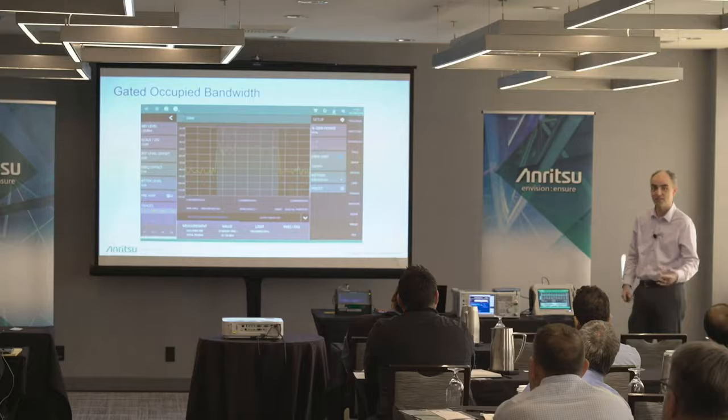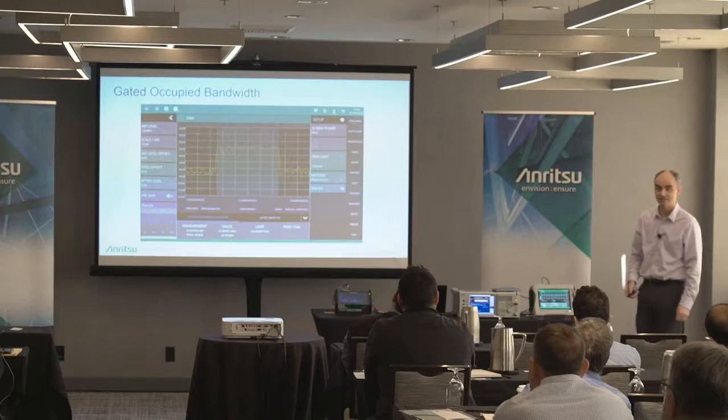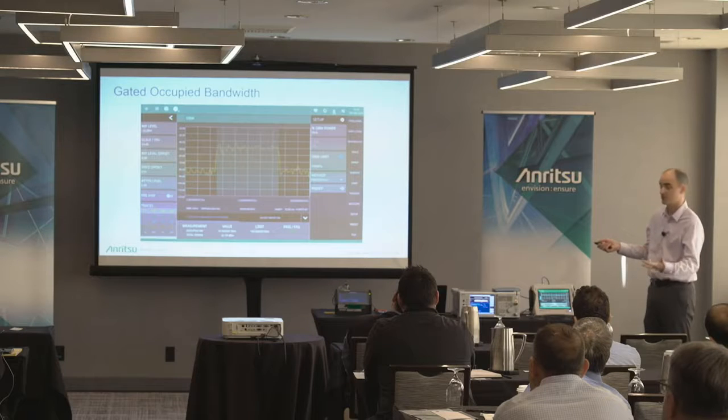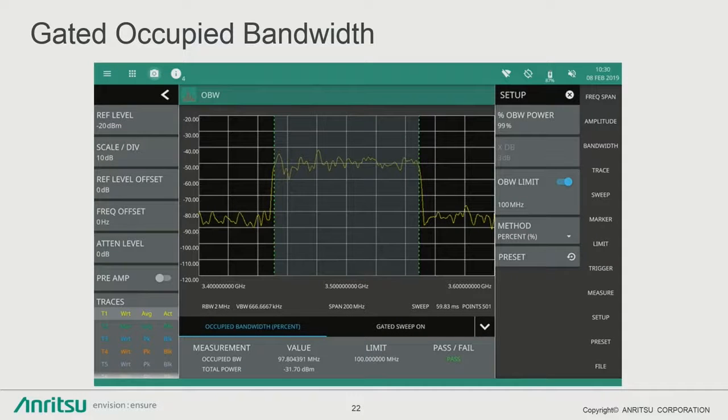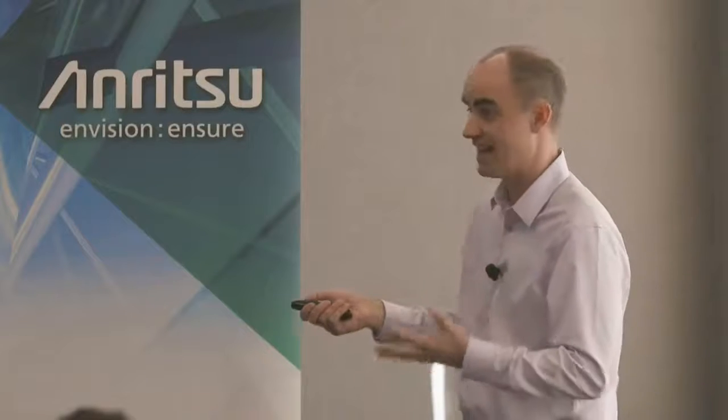Uplink or downlink? Downlink, right? So downlink, it has to be on, right? So I have to be able to make sure that that signal's on. So I know it's on, I know I'm using it. Now, I have seen, this is a little bit different because this was back in the 3G world, but I have seen, and you guys may have seen this as well, where you have a signal that looks like this, but then it rolls off at the end. You just have this weird roll off at the end. Filtering on the signal didn't pass all the way through, so because the filter had a sharper roll off or an incorrect roll off, it was actually blocking part of that signal before it even left the radio. So these are ways to verify that everything is working as it should, okay?